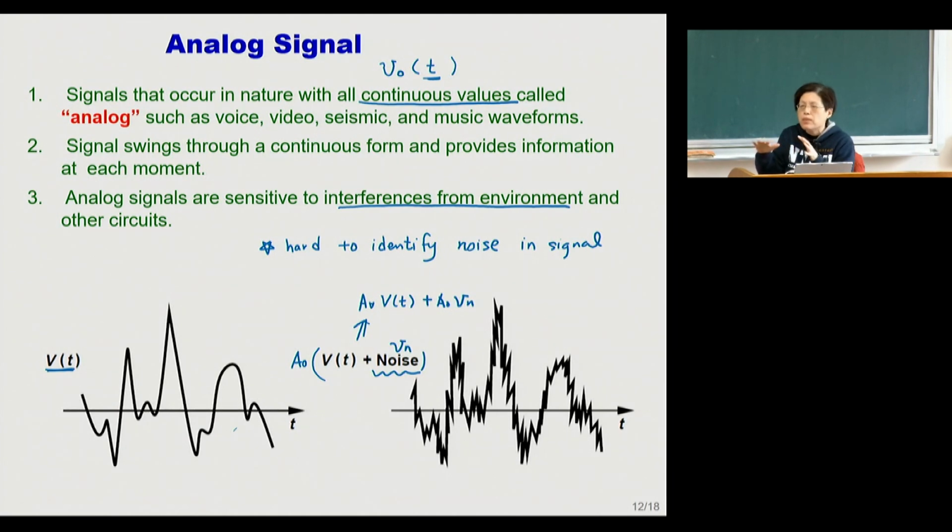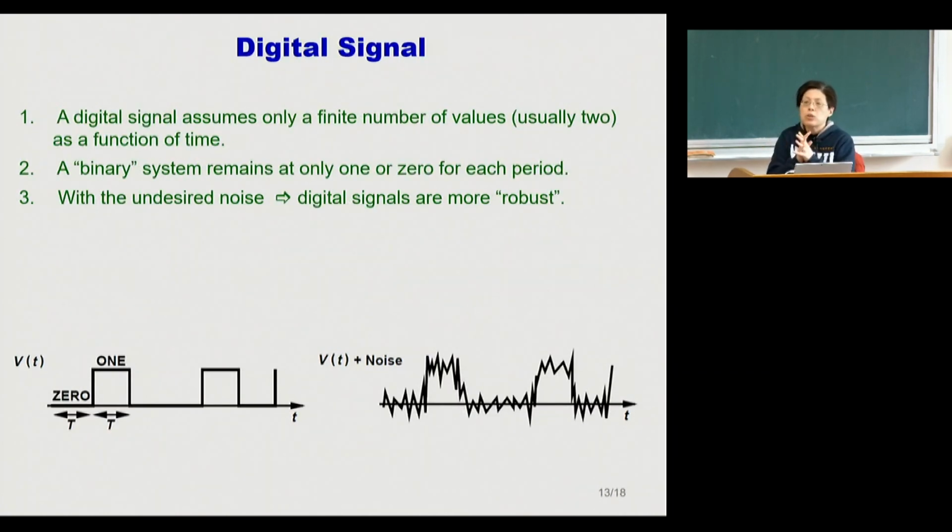Of course, there are some ways of dealing with fundamental or input noise, such as differential design, but only to a limit. So in order to clean up the electronic system, most electronic systems turn into digital systems. What do we mean by a digital system? I particularly assign acceptable levels, meaning that only a finite number of values are recognized.